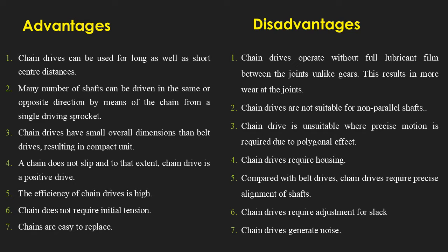And when you compare with belt drive, it has very small dimensions. It is small compared to belt drives. Hence, it will result in a very compact unit. And as I said, the chances of slip in chain are very less when compared to belt drives. So chain drives can also be termed as a positive drive, similar to gear drives.